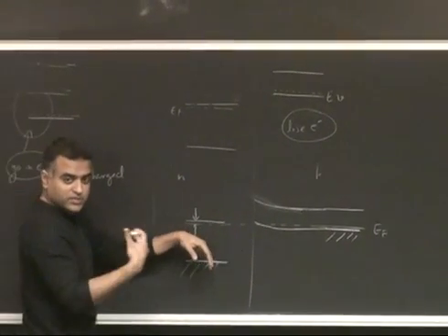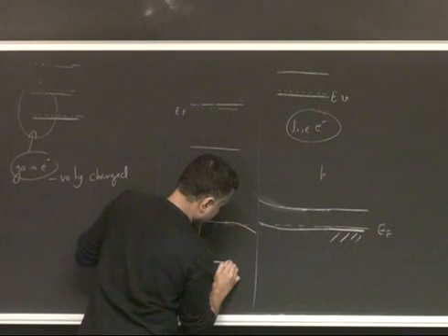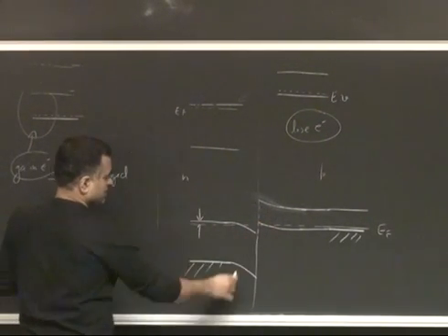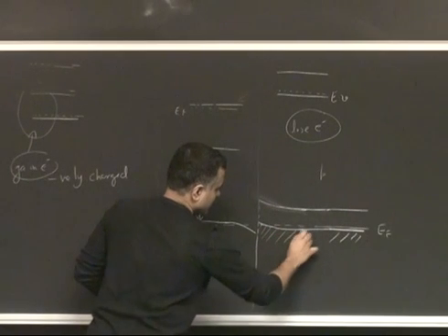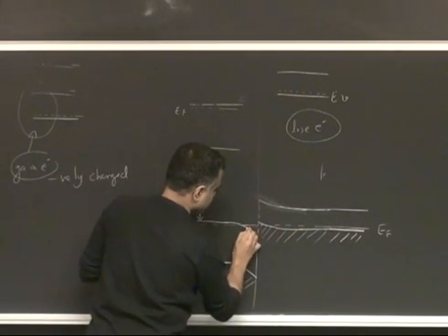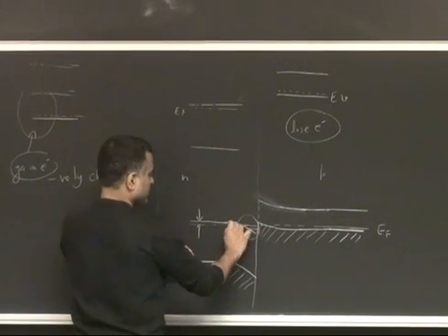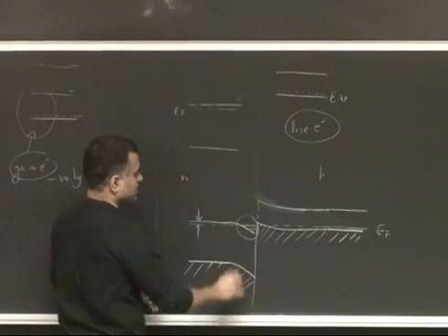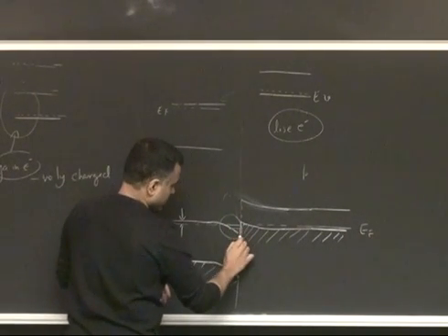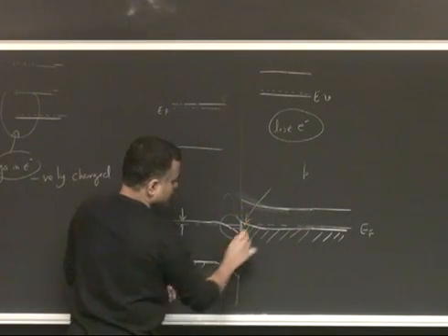It's going to accumulate electrons that were dumped out of there. So it's going to bend down. And you have kind of a broken gap junction here, where these are all valence band states, and then what you will get is, in this little window here, a triangular region, and we have quantized states here. So you will get an electron accumulation layer here, and you will get a hole accumulation layer here. So there are, in this little window on the right side, a lot of holes.